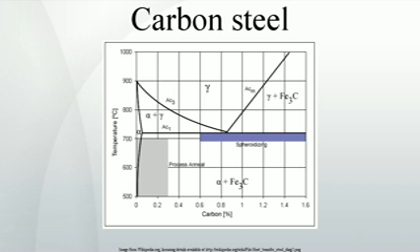Low alloy carbon steel, such as A36 grade, contains about 0.05% sulfur and melts around 1426 to 1538 °C, 2599 to 2800 °F. Manganese is often added to improve the hardenability of low carbon steels. These additions turn the material into a low alloy steel by some definitions, but AISI's definition of carbon steel allows up to 1.65% manganese by weight.